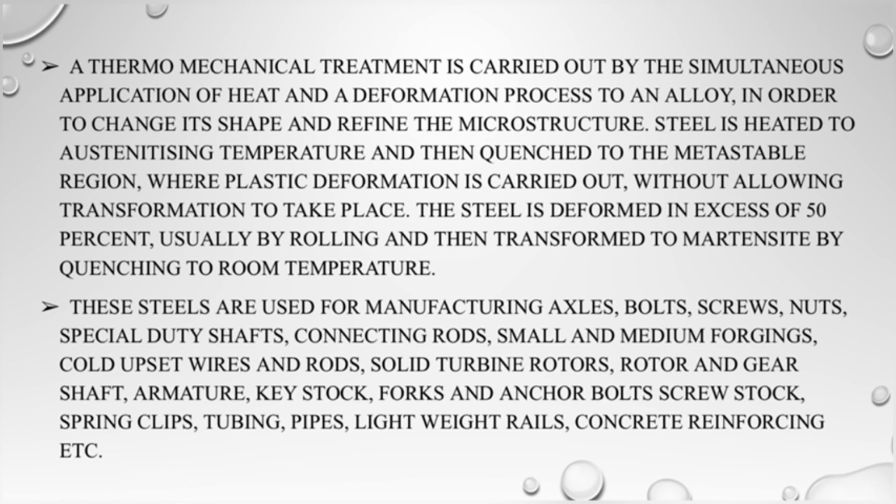After heating to a certain temperature, the steel can be deformed into many shapes as required. It can be rolled, it can be beaten into swords and everything. And after attaining the desired shape, this steel is quenched to normal room temperature by dipping into some oil, or by suddenly reducing its temperature, which will temper the steel.